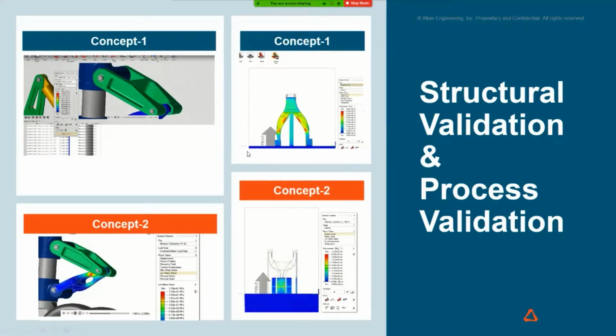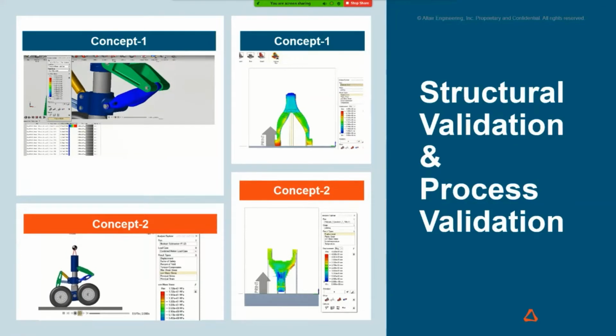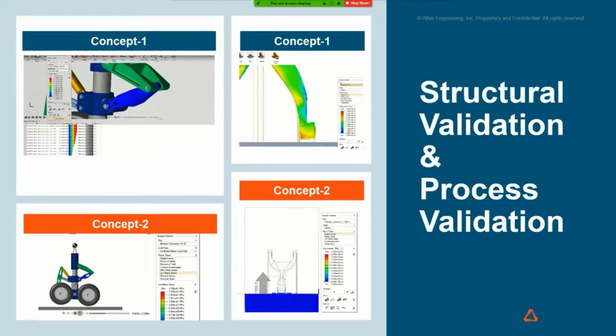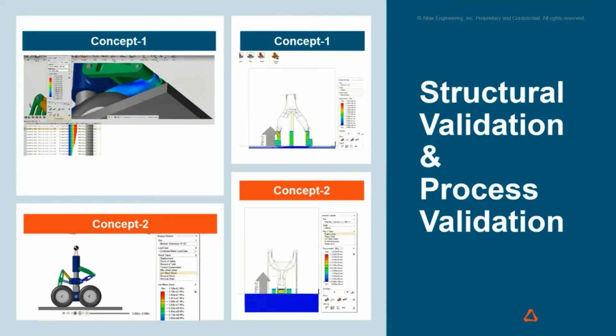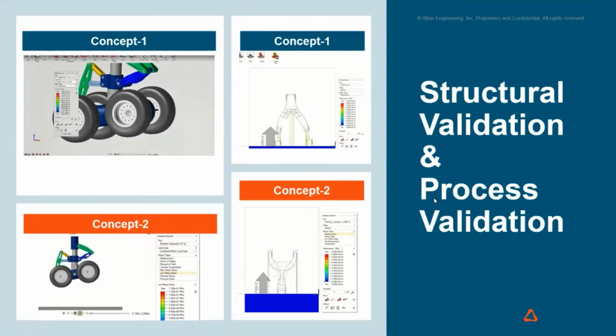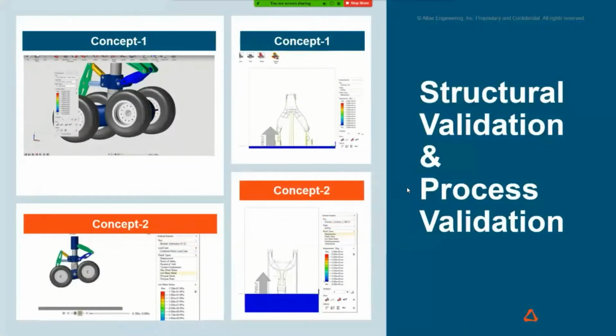You extract your load, apply those loads, optimize those concepts, and then you re-verify those concepts for structural as well as manufacturing process requirements, right? And that's the complete workflow of your design for additive manufacturing with Inspire.